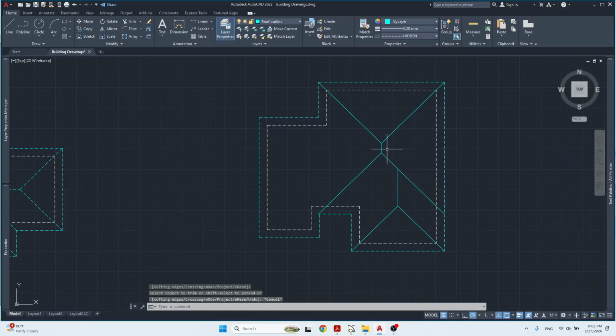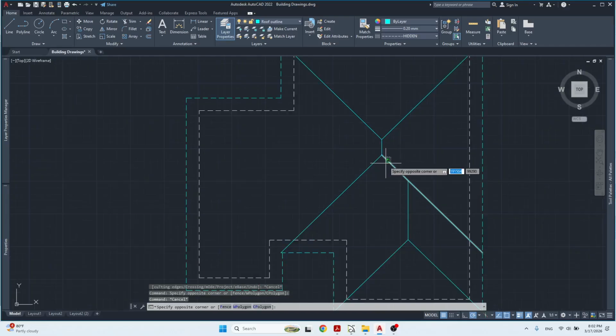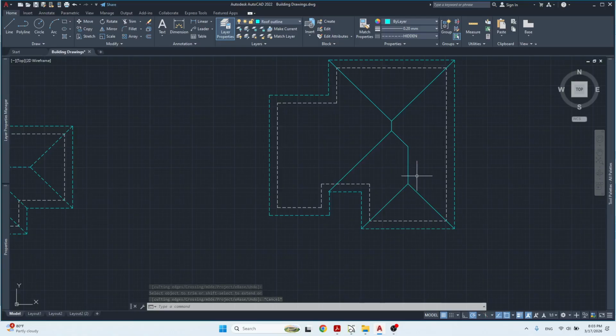Why this side? Because remember we said, imagine you have your ridge at the highest point, your highest ridge, and then you have a hip rafter coming down, and then this hip rafter meets a ridge, so it stops right there. So we're going to get rid of that hip rafter. It stops when it meets that ridge. If you think of it that way. So that now leaves this entire side over here that slopes this direction. If rain falls, all of it slopes down, runs off this side, going from left to right. All right, so this side is finished.